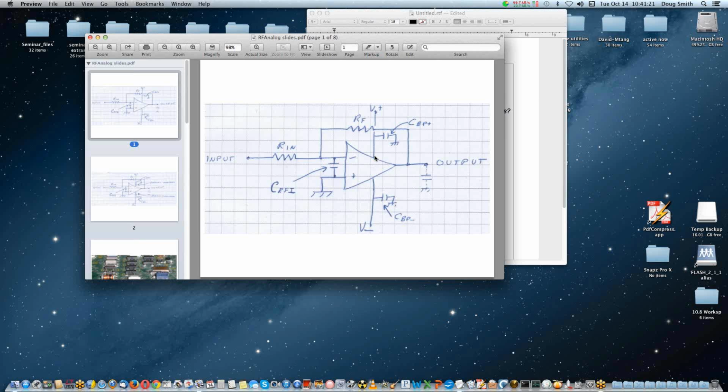And 2 gigahertz is important because that's near the cell phone upper band and it's near the wireless band, both of which are big things these days, and your product might be right next to one of these gadgets, even though they're not powerful transmitters. The distances can be very small, and so it gets into these things. But I think the feedback network probably would work up to the point where the operational amplifier is characterized too.